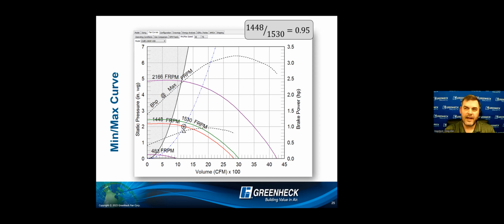And if that number is not a good one for me, let's say I'm going into a construction where it is very likely my ductwork is going to move multiple times from design to reality, right? And there's a chance that my static pressure is going to do this, or there's a little bit of system effect here. Is 95% a good bet to make sure that this project goes without a hitch, as much as possible, and moves the air I need it to move? If 5% turn up is not a happy place, maybe you like 80%, right? I want 20% turn up, 60% turn down. I want to be in that range.